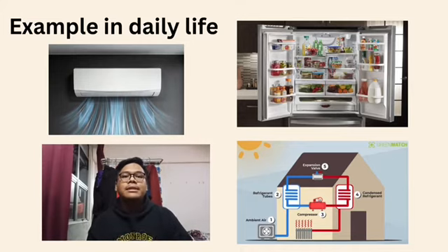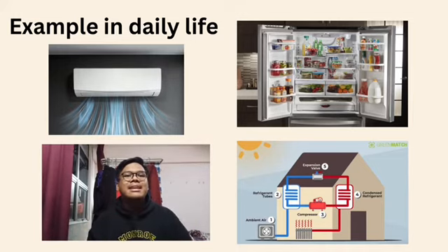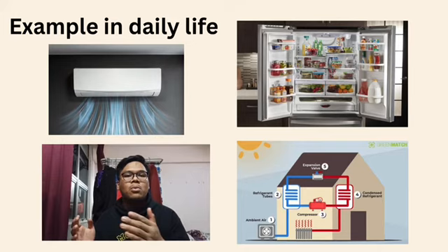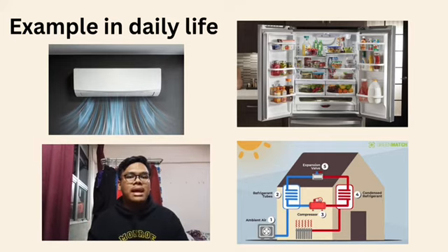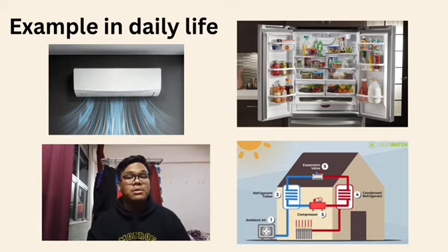Mechanical energy converters that turn mechanical energy into heat include refrigerators and heat pumps. These are typically categorized as closed systems. The temperature of a gas increases when it is compressed. The environment can then get heat from this hot gas. Since some of the compressed gas's heat energy was lost during the hot cycle, when it is allowed to expand, its temperature falls below what it was before compression. The cold gas can then absorb heat energy from its environment, and an air conditioner functions on the same principle.